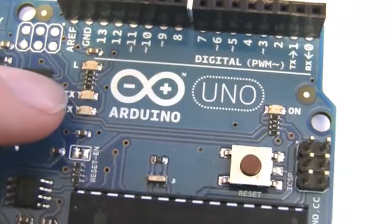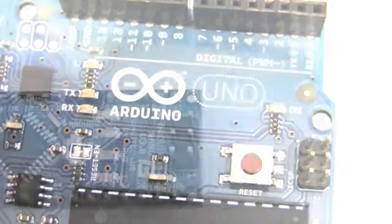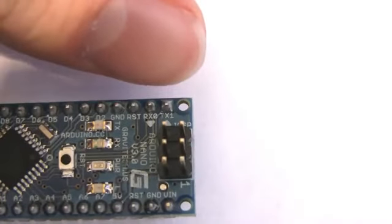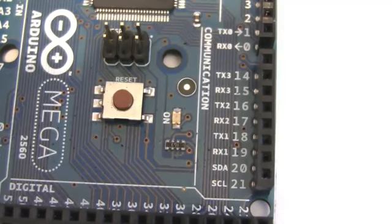When you do this, you'll notice that the TX and RX LEDs will flash to indicate that you're sending or receiving data. The same story holds true for the Nano. Here you can see the TX and RX pins on the Nano. The Mega is a different story. You'll see that there's still TX and RX on pins 0 and 1, but there's also 3 more serial interfaces that you can use for communicating either with other Arduinos or just any other device that accepts serial communication. This comes in useful later on if you want to be able to simultaneously program the device and have it plugged into a separate serial interface.